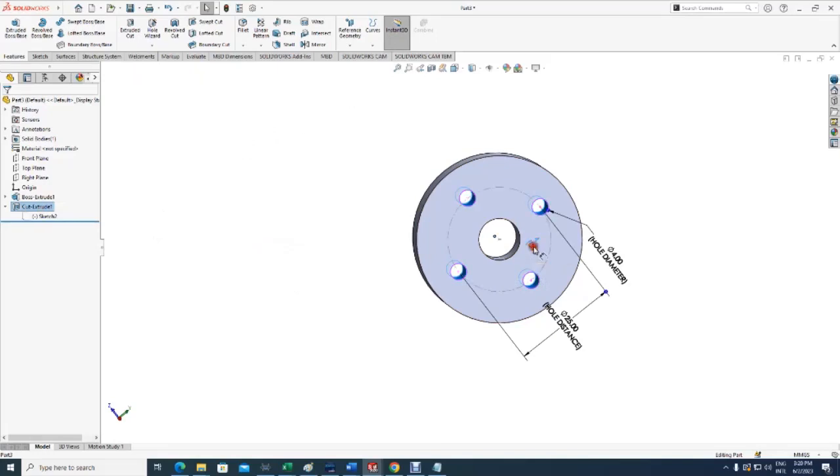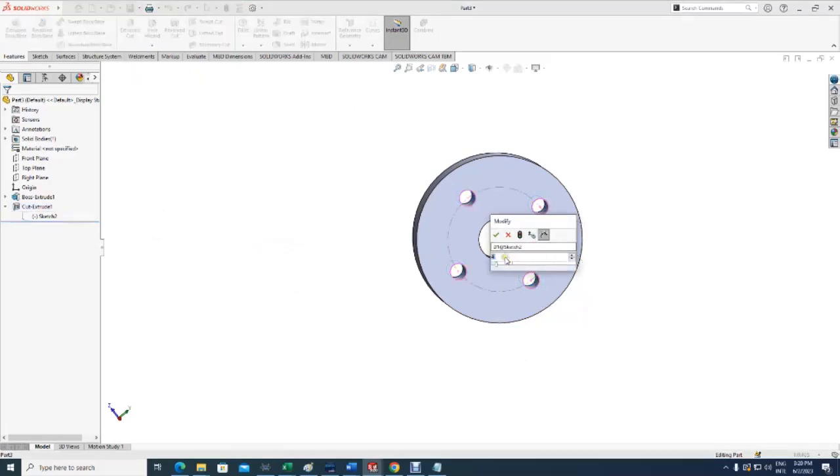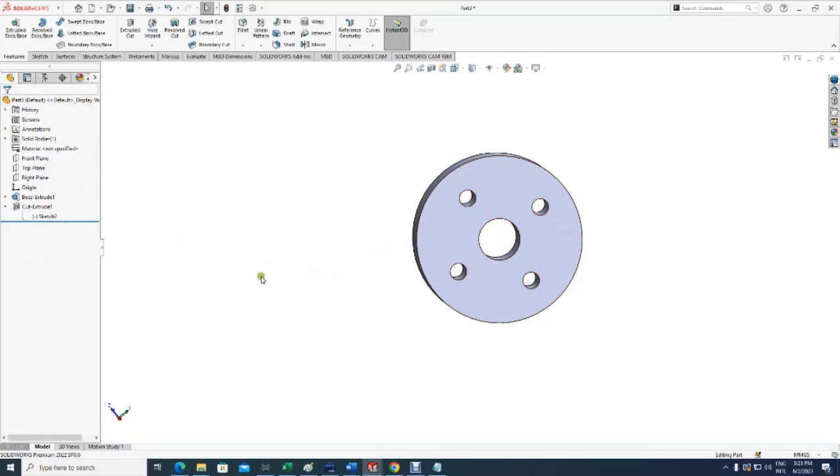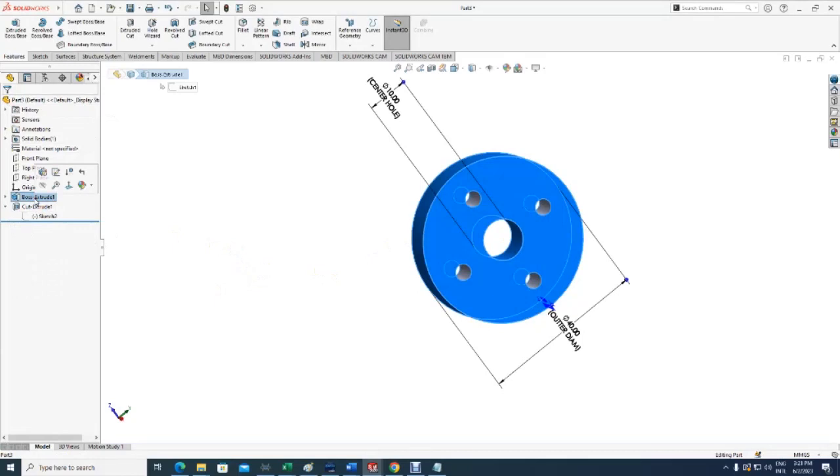Double click as fast as you can. Now you have it there. You don't want to change the number of holes, that's okay, but you want to change this and put a meaningful name here, like number of holes. So we accept that, and now when we touch anything here, everything will start to have kind of a meaningful name. And so that's on the first sketch.